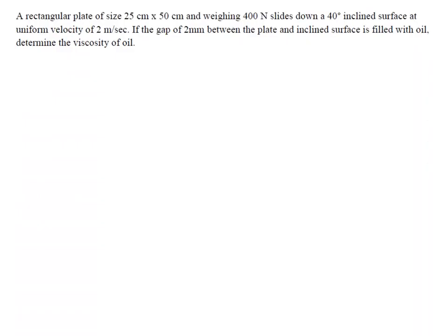Next problem: a rectangular plate of size 25 centimeters by 50 centimeters, weighing 400 newtons, slides down a 40-degree inclined surface at a uniform velocity of 2 meter per second. The gap between the plate and the inclined surface, 2 mm, is filled with oil. Determine the viscosity of the oil. Again the rectangular plate is the moving part, whereas the inclined surface is stationary, and the gap between them is filled with oil. That gap is about 2 mm, so y is 2 mm.